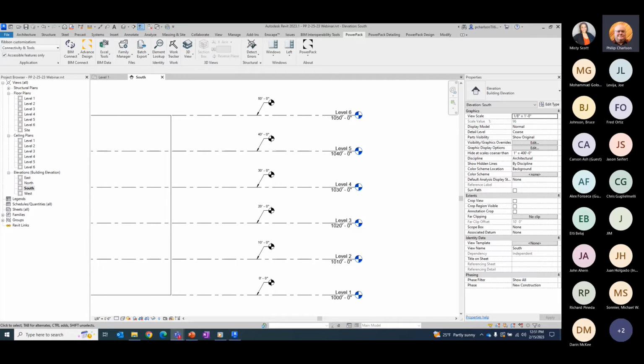Does it have an automatic function to tag size, shape, and elevation of HVAC equipment? No, but you should be able to have that within Revit. It might be some Revit customization that needs to happen. You probably just need to customize the tag.